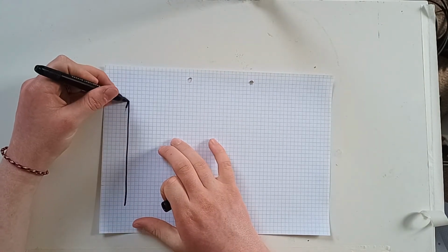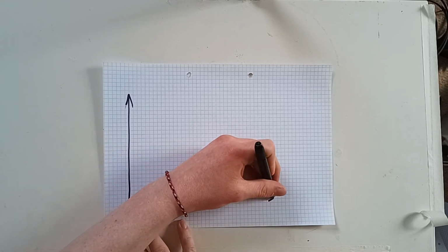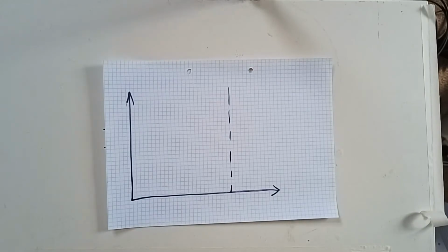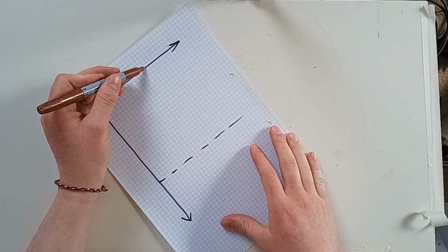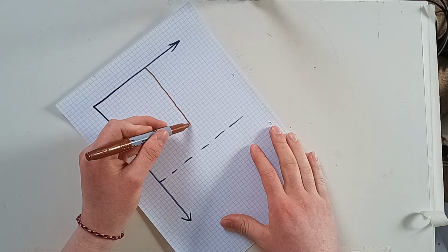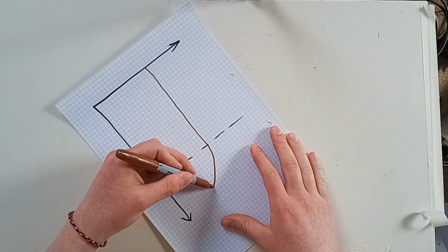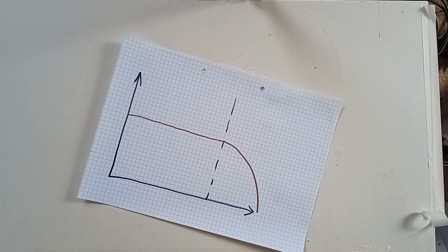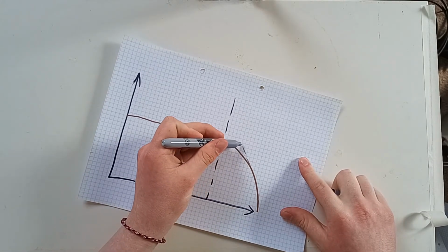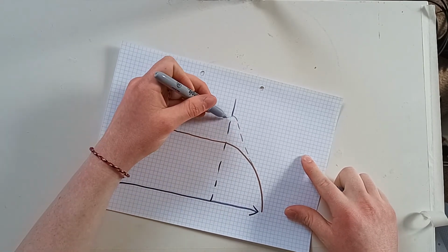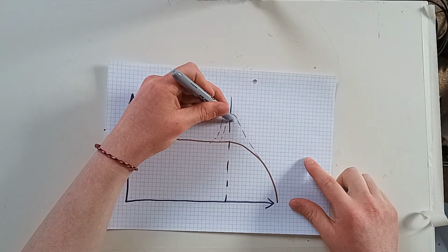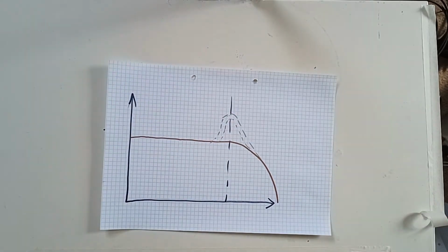And I'll sketch that again just to make it more clear. So here is our cutoff point. Then we have the signal, which I'm going to start using the slope from first and second order filters. And then our resonance would come up on top like this. And you can control this resonance so you can end up with different sorts of peaks, or different heights of peaks, rather.